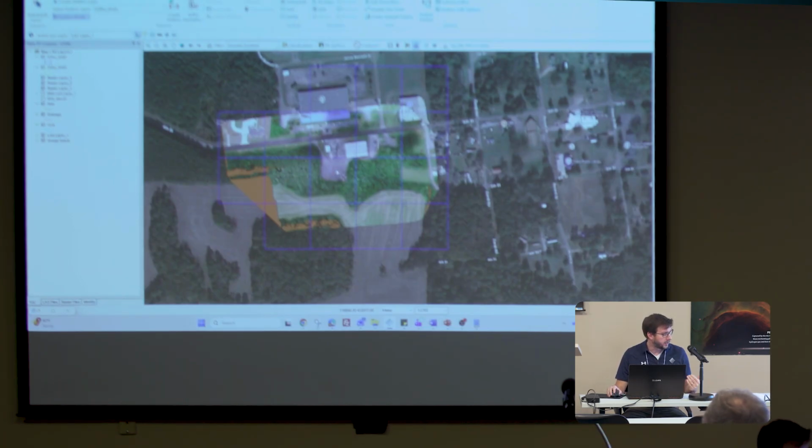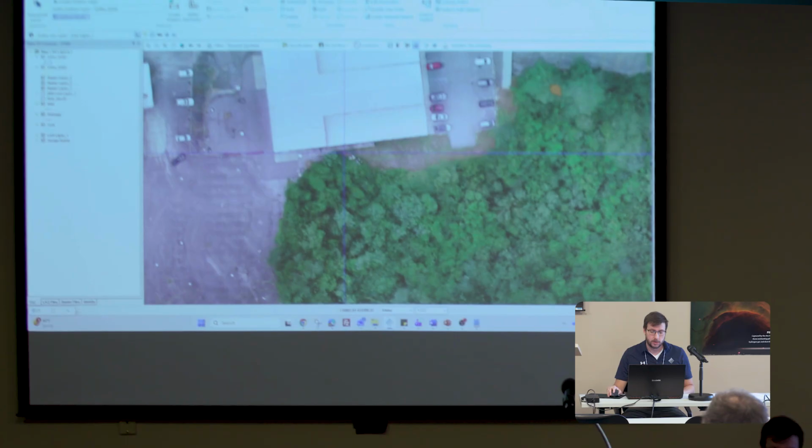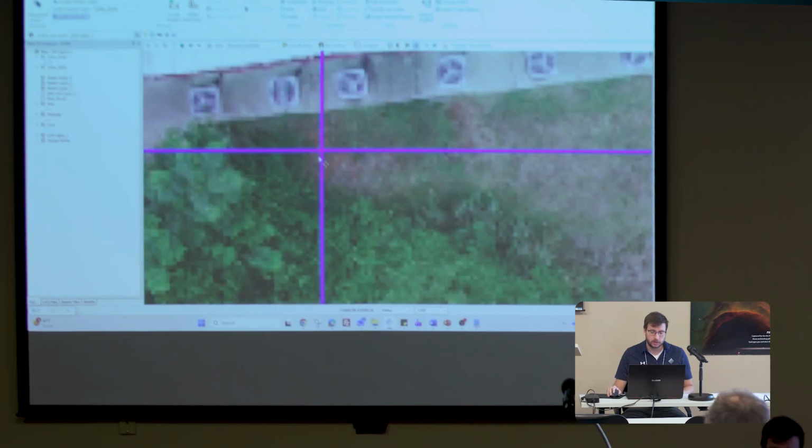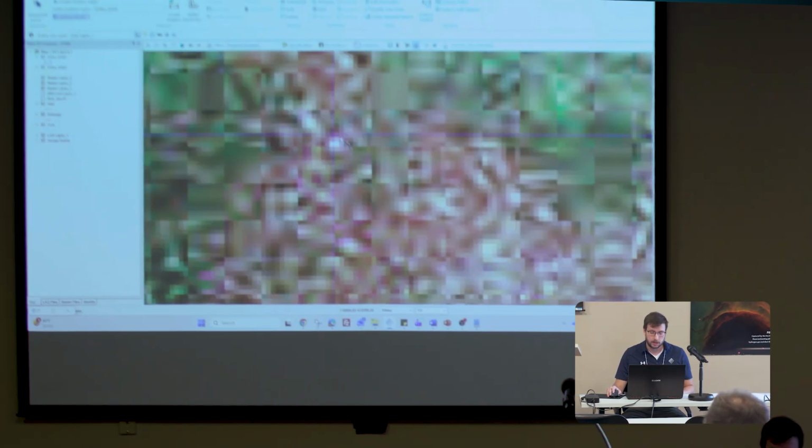One of the things I have in this exercise is telling you how to... we've created this grid. I'm just going to go ahead and zoom in. If you want to zoom along with me, just zoom into where this grid meets the raster pixel. I'm just going to zoom way in. See how it's offset? You don't have to do this with me. I'm just going to show you. This really has to be lined up perfectly with the edges of the pixel so you don't get those